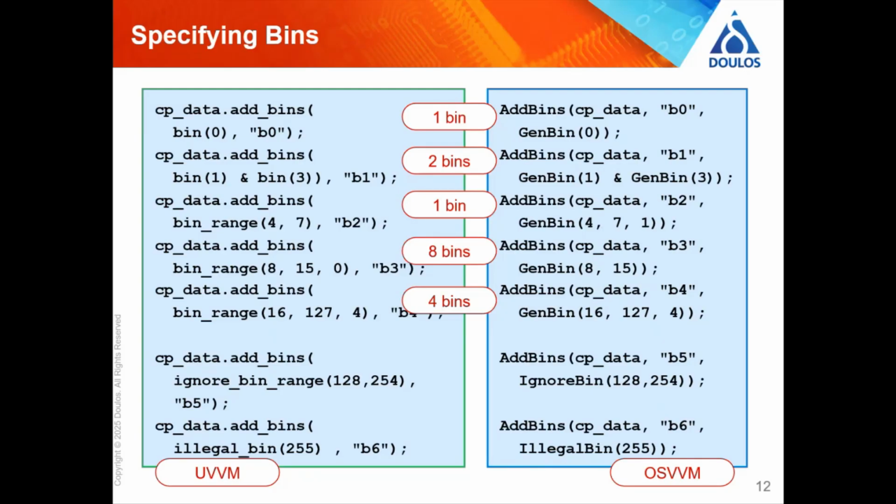So if the coverage is trying to get in the way of saying, is that a valid value or not, there's a good argument for saying, just stay in your box. That's not really what you're there for. The checker should be handling that. And it could lull you into a false sense of security, thinking the coverage will handle whether you've got illegal values, but it's actually not done as comprehensively as it would be in the checker. So personally, I'm not mad keen on the idea of illegal bins. I would think just keep the coverage doing coverage.